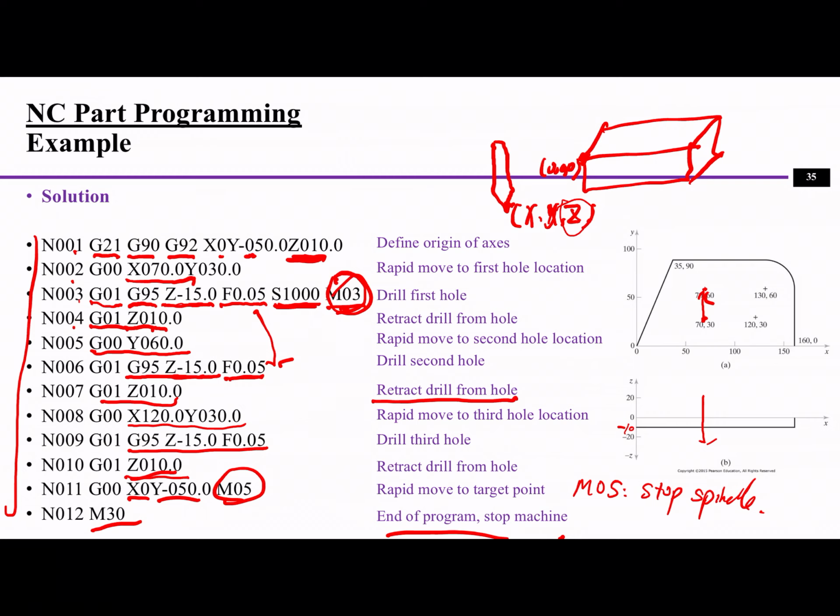And when you have a really long program, with thousands of lines of G code, they are all basically the same idea. You simply tell the machine where to go, specify some parameters, and then tell the spindle what to do.